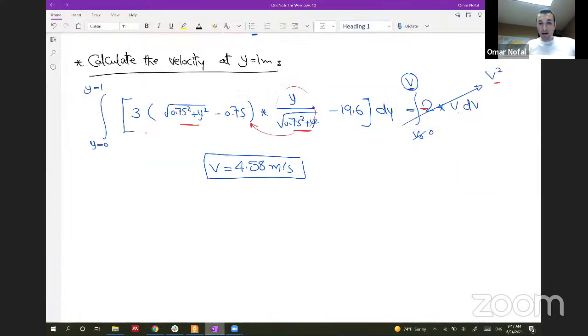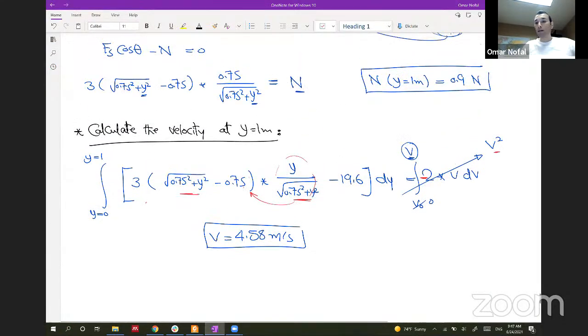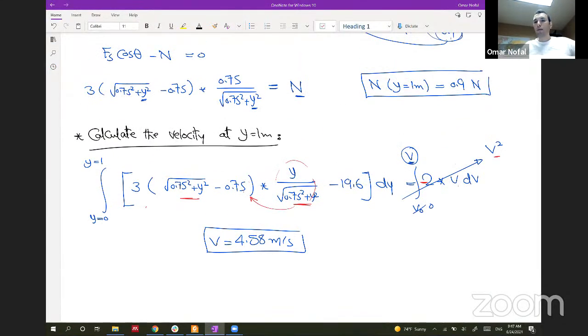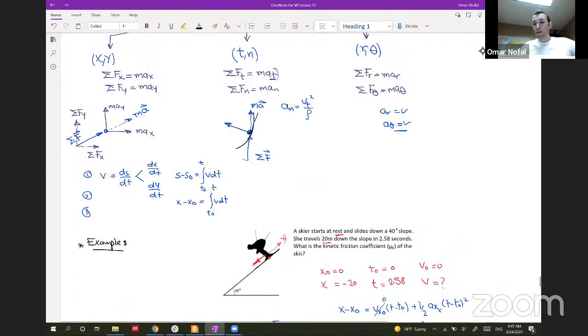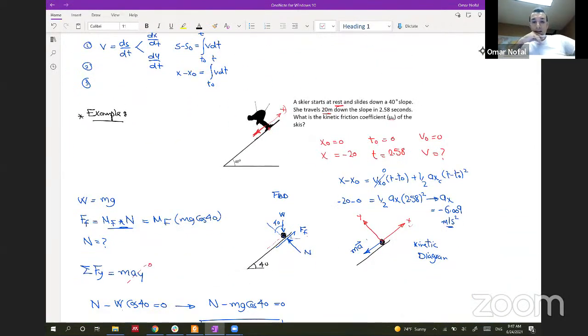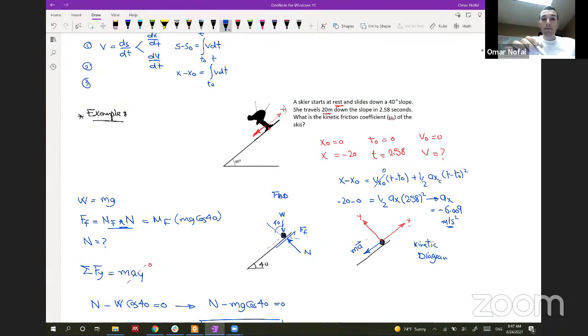And today we will continue with Newtonian kinetics. I want to make sure of one thing for the problems that we solved yesterday. Yesterday, I told you to create a free body diagram like this one, and one that has a kinetic diagram. On the kinetic diagram, you construct the x and y axes and assume a direction of the motion. Here we assume that the body is moving in the negative x-axis, so MA should be negative.